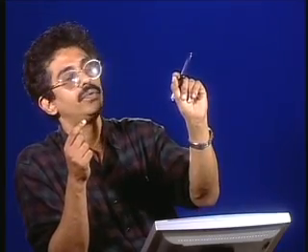On the other hand, you need to determine pairing. This is very important, that is, which manipulated variable you will choose to set up a loop with which controlled variable. This is called pairing outputs to inputs. This is an interesting point, and people have various methods. We did not study them, but this needs to be done.